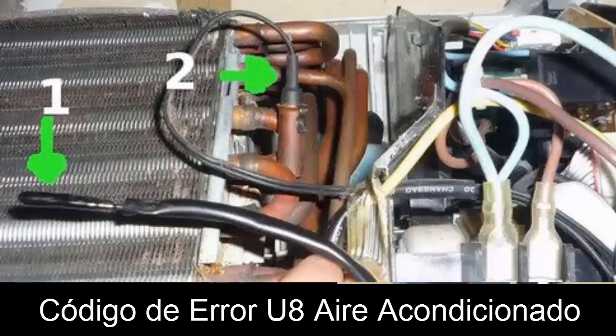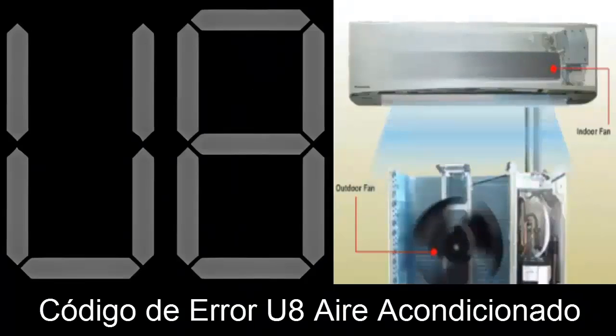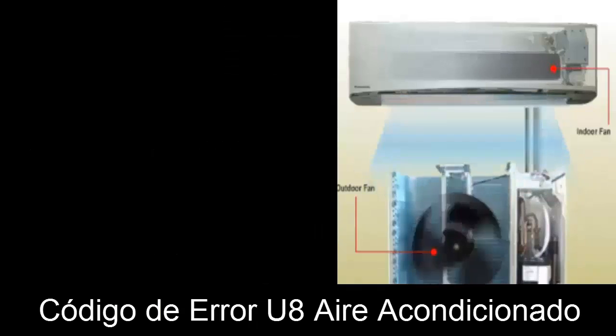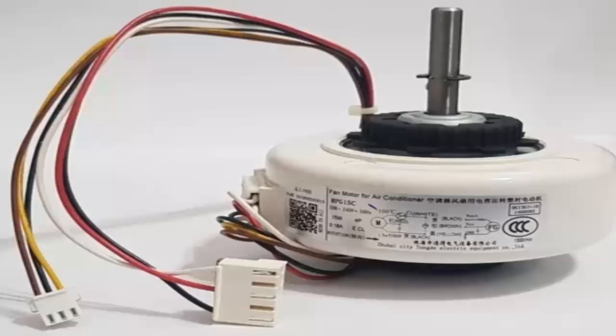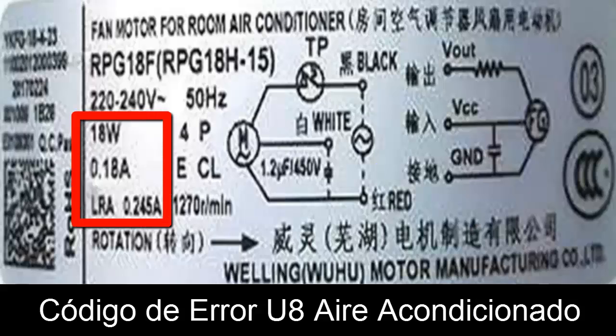3. Check the electrical connections that power the fan, paying special attention to the thick cables. Ensure there are no loose or damaged connections. 4. If you can activate the fan, check its current consumption using a clamp meter and compare it with the fan motor's regular consumption value, known as RLA. The measured consumption should be very close to or below the regular consumption.